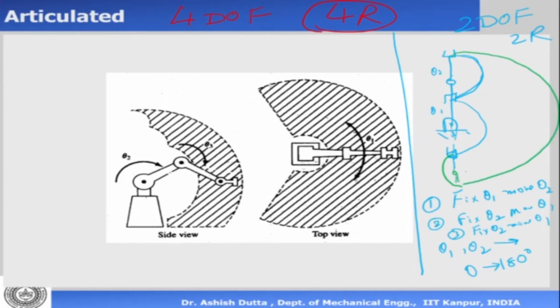That is the shape of the work volume. Now, some things we have seen. The first thing we have seen is that there are 2 circles inside and there is 1 circle outside for a 2-degree of freedom system. Let me explain it one more time. This is a planar manipulator, 2 degrees of freedom, 1 link here, 1 link here. This is my theta 1, that's my theta 2.